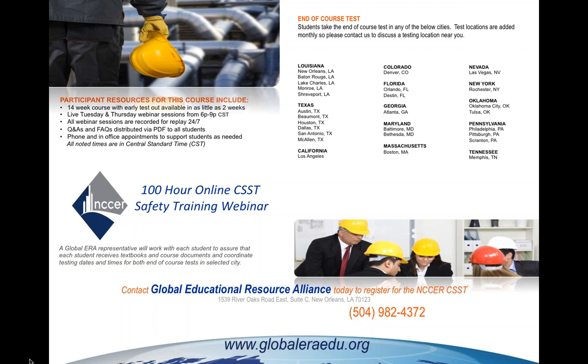Assume a safe and comfortable position before we start using a power tool. Ergonomics is important, but also tool safety, right? It falls into both categories. Don't distract others, and don't let anybody distract you while you're using a power tool. Be sure that any electrical tool is properly grounded before we use it, or make sure it's double insulated. Be sure that power is not connected before performing any type of maintenance or changing any accessories. The first thing we want to do is unplug that tool, right?